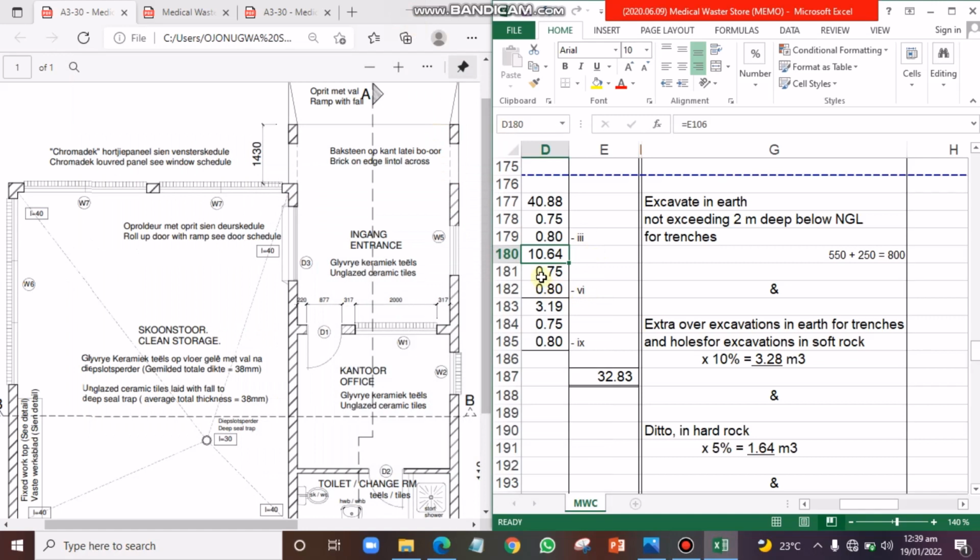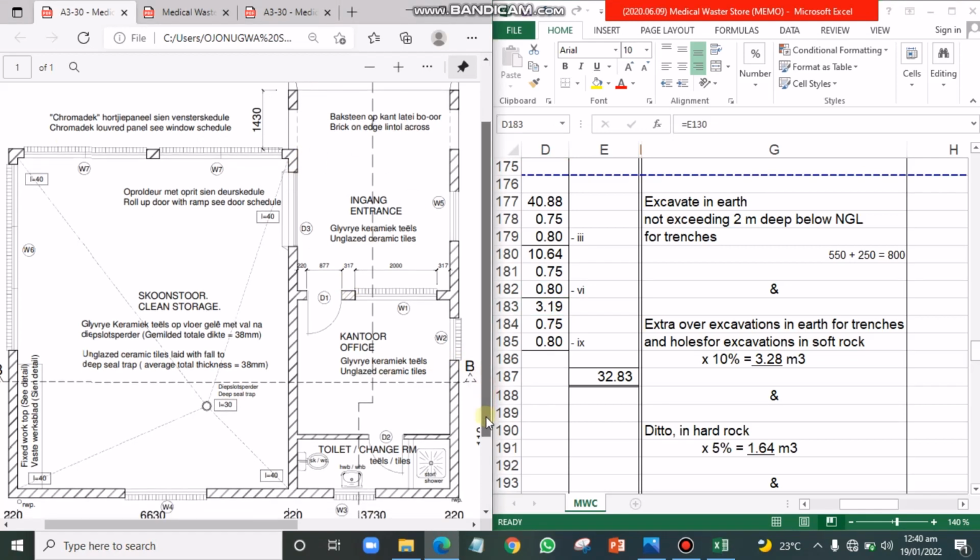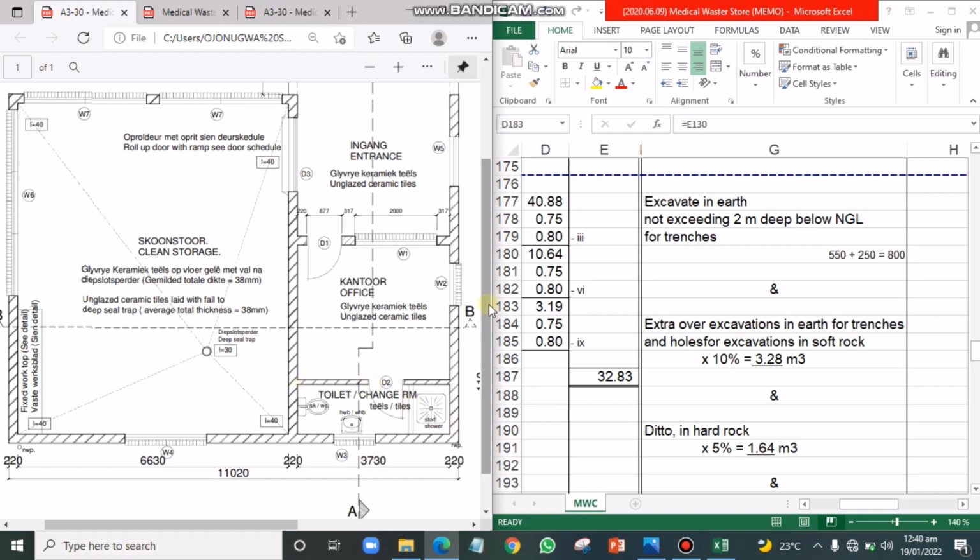Okay. So like I said, this is for the external. Remember, the widths are the same, the depths are all the same. All that changes is the length that we have already calculated in the collection. So this is the external. This is the 220 block in the internal part of the building. Then this last one is the calculation we did for the 110 block wall in the building. So this is for the internal block wall, 3.19 internal block wall, which is 110 here in the plan.